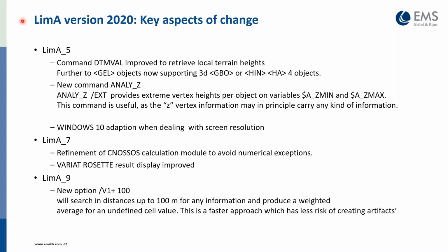from a particular area, a particular contour point, in order to create more accurate contours more quickly and easily. So you know that the denser you make your contour points in a grid, the more accurate your interpolated results are, but the more calculation time you require. You can reduce the calculation time by having a lower number of calculation points and a coarser resolution. But when you try and do noise contours on that, you sometimes get some strange results.